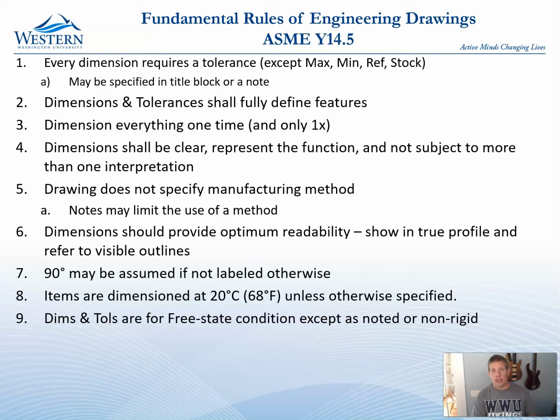Dimensions and tolerances are in the free state unless noted or unless it's non-rigid. And so what this means is you can't measure something while it's in the fixture. It has to be out sitting on the table in the free state.